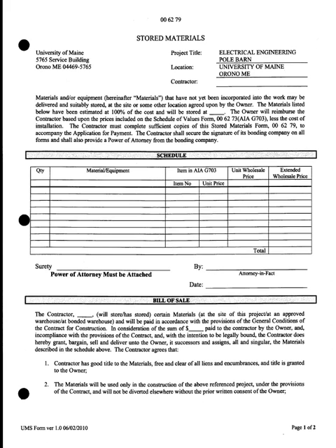Consent of surety to reduction in or partial release of retainage. We hold 5% normally of the total construction cost from the contractor until the job is totally done and we're satisfied that it meets all of our requirements based on the specifications in the drawing. If they've left something out, we're going to keep that 5% to make it worth their while to come back and fix it. Otherwise, if you pay them everything and it's still not right, you're never going to see them here. Not easily anyway, so there'll always be something going on.